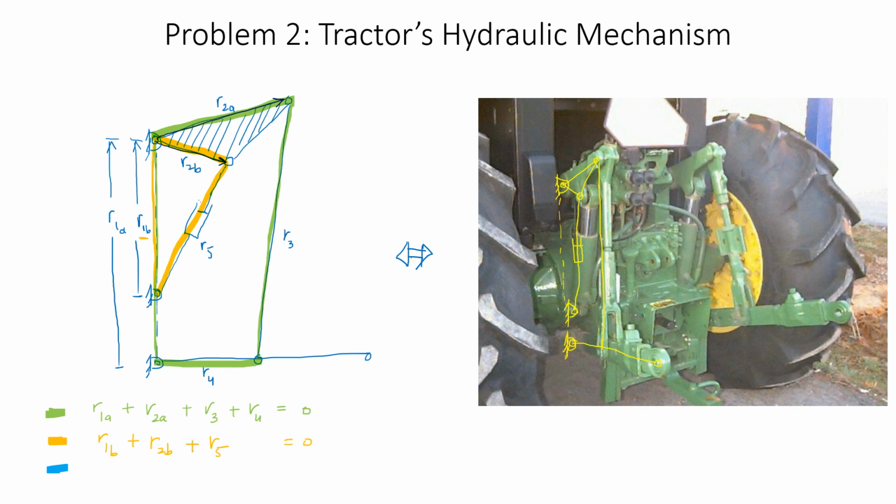The third one, which is the constraint equation, exists because of the ternary link placed over here. I can see that you have a fixed angular displacement, and this is the angular displacement that you can specify. So theta 2b is equal to theta 2a plus, let it be, alpha 2.